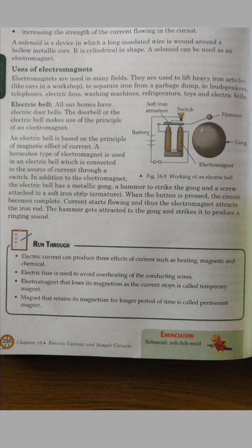Now as far as the use is concerned, the important use that we have in our syllabus is the electric bell. As you can see clearly in the diagram, we have a battery, a soft iron armature, then a switch, hammer, gong, and a horseshoe magnet, which is a horseshoe-type structure wound with the wire. What happens the moment we press the key is that the circuit gets completed, the armature gets attracted towards the horseshoe magnet, and thereby the hammer hits the gong, and this results in opening the circuit.